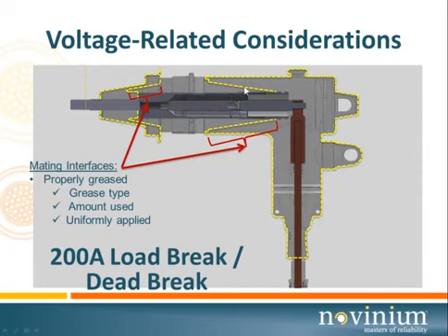It starts to buckle. You can't see it, but embedded in that buckled area is a minute amount of air. We've already talked about air. It has a lower dielectric strength than the rubber. You can't have that. Just because you apply the grease to 90% of the surface, if you don't apply it to 100% all around, even on the bottom where you can't see it, you're not doing a good job of uniformly applying the grease.